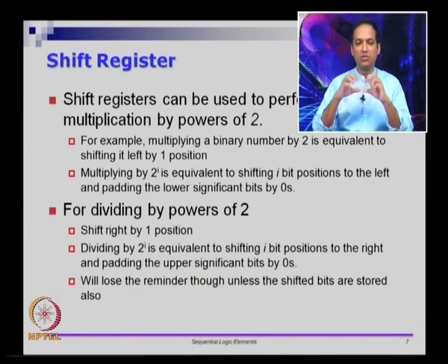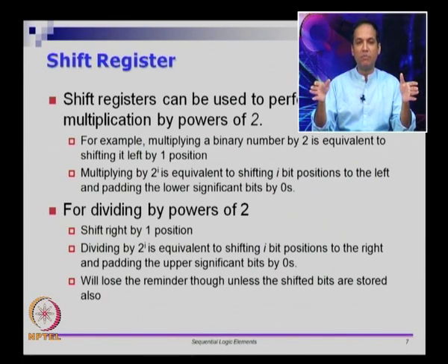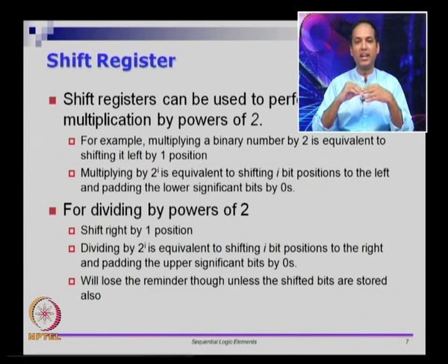If I put some value n in a 5-bit register and right shift it 2 times, the equivalent value will be n divided by 4, or rather, you know the ceil and floor functions, it will give you the floor of n divided by 4, which means the integer that is lesser than n by 4 and the closest to it.